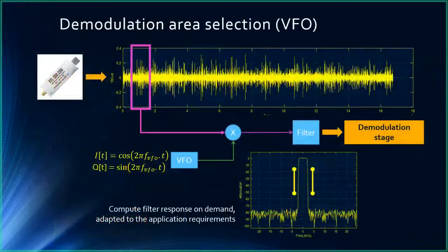What is a bit more difficult now is the demodulation. Basically, you see that from the yellow time domain plot above, that's what is coming out from the USB or other connection from your external hardware. You receive a series of numbers, and these numbers are, as I said, the measurements provided by the ADC, the analog to digital converter, but this samples over a wide band. I mean, the full band that is seen by the receiver, the IF band. So you need to extract the portion of signal, the area you want to decode.